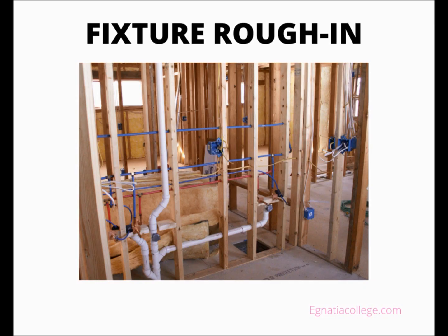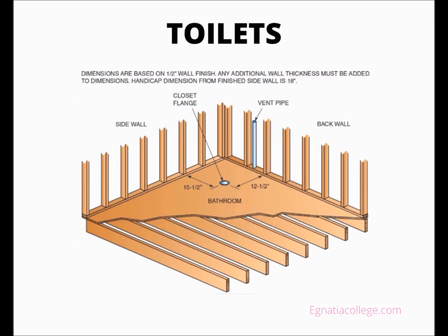In other words, pipe sizing is based on codes and then is adjusted according to job site preferences. Many drilling and notching codes do not allow an adequate hole size to install a 1 1/2 inches pipe, so a 1 1/4 inches must be used in certain situations, such as serving a lavatory. The following information focuses on specific rough-in requirements based on common heights and distances.